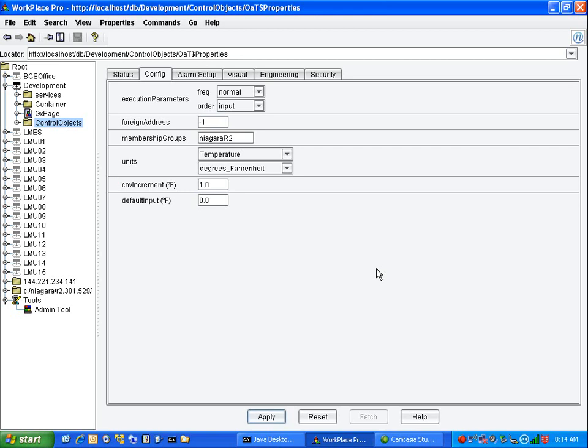And what happens is if I share this to like 50 controllers that are looking for outside air temperature, that will save a whole lot on the bandwidth of your communications, whether it be BACnet, Network 8000, or LAN. By putting in a COV in there, you're not writing constantly to that input of the controller as it goes down to the controller. So it'll only write when you exceed this COV value.